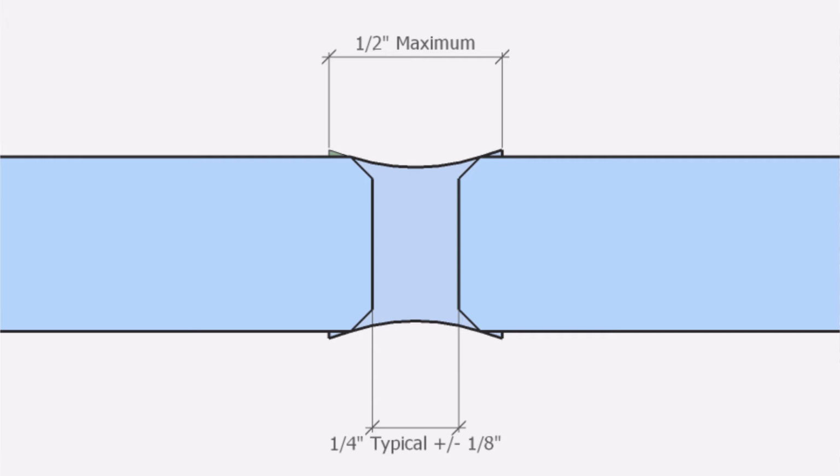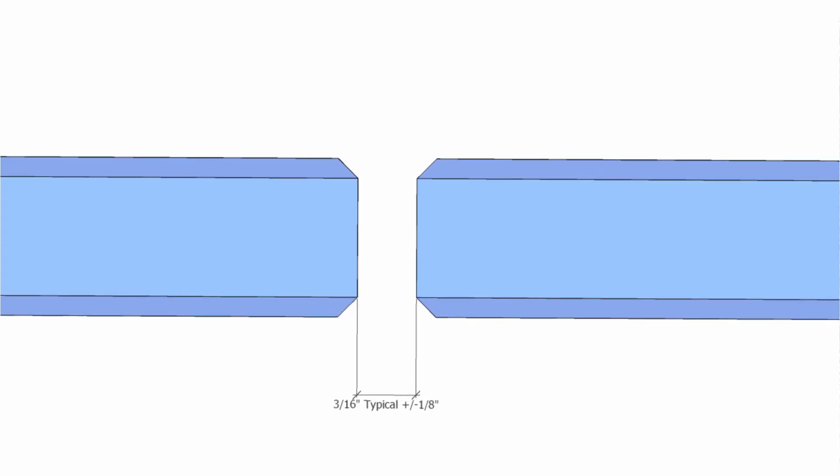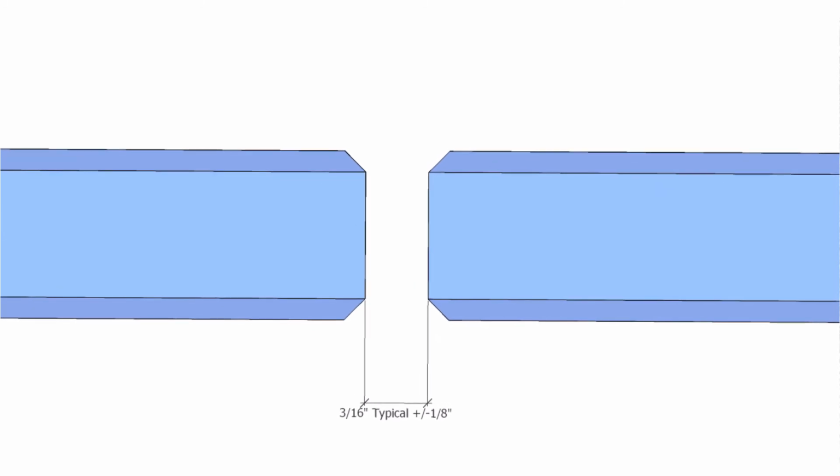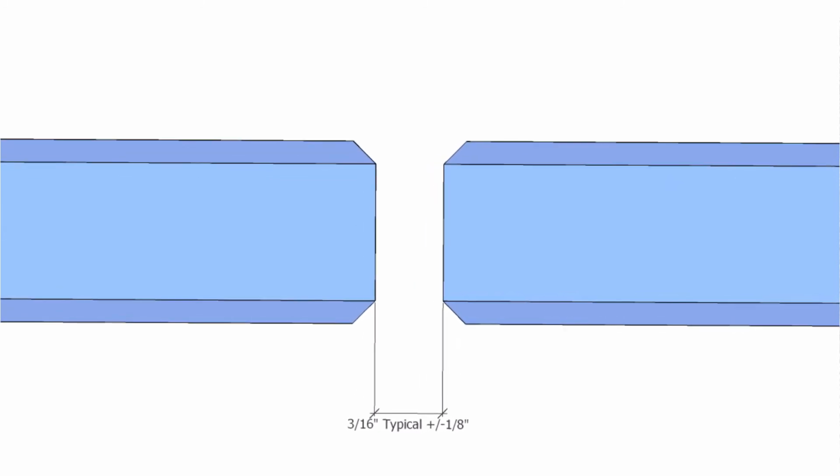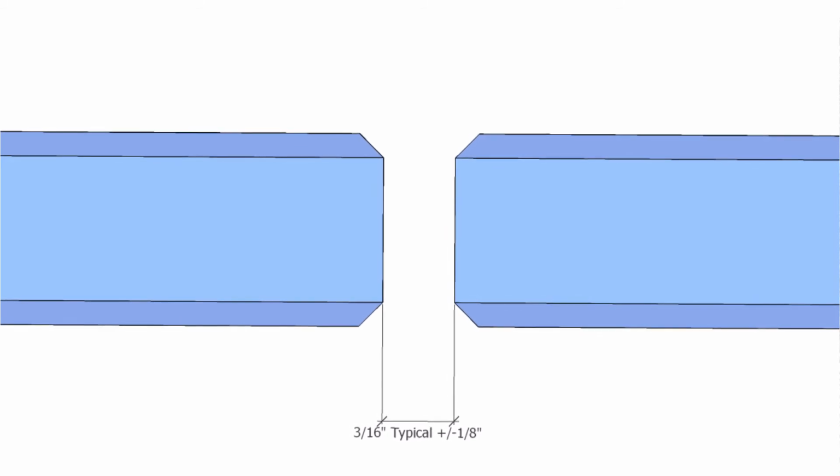Size between the glass panels can vary by 1/8 of an inch per the uncertainty in the cut size of the glass material. Next, we have a joint where no material is provided. We only have air between the adjacent panels, and they're not connected to each other. This type of joint is relatively common, although we understand that it does not allow us to meet the building codes unless we use a thick enough glass to limit the deflection. Deductions for this size joint are going to be 3/16 of an inch.